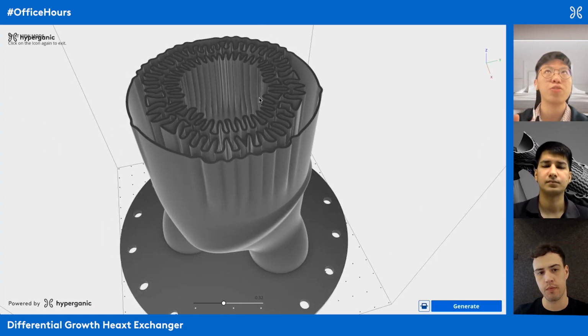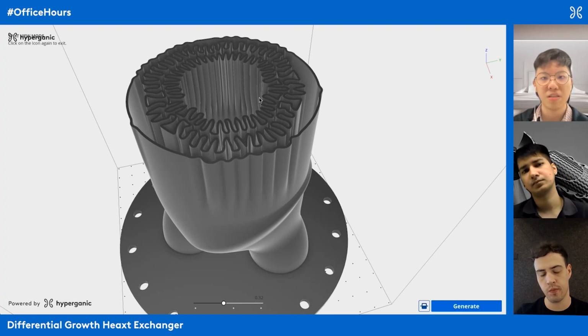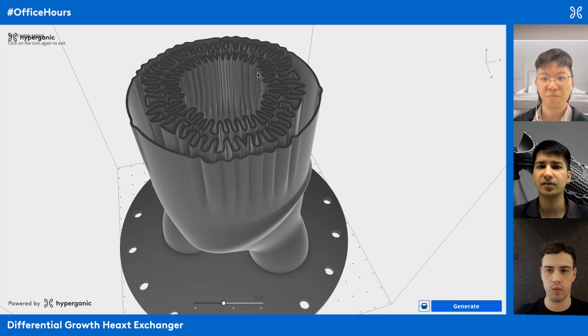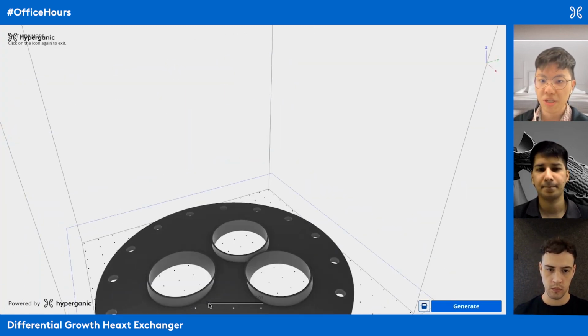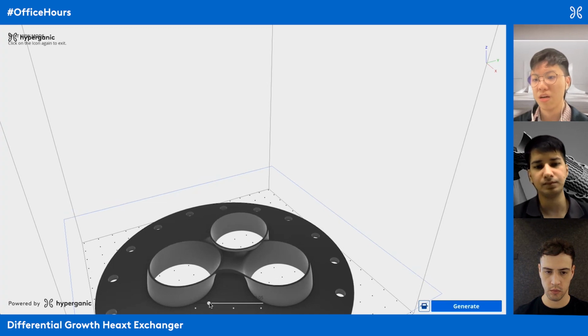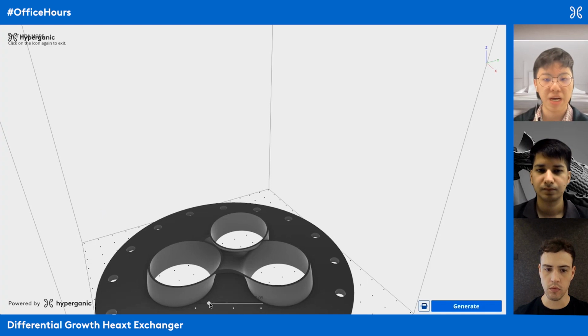Primarily that the cross-sectional area is going to be the primary factor for my pressure drop, which may not necessarily be the case, but it's going to be good enough for a first initial guess of the behavior that this differential growth would take. And is that also the case in the transitional area? Yes, that's also the case for the transitional area. I'm primarily looking at the colliding region, which is where my radius would start to expand, and where it's totally encompassed would be the final biggest radius that I would possibly have for each given pipe.